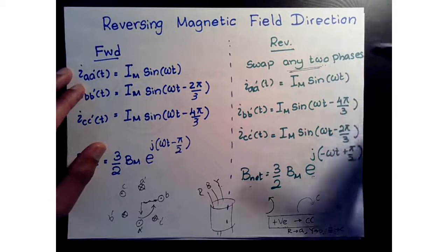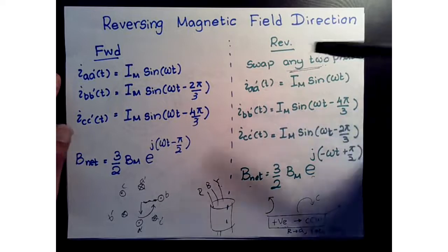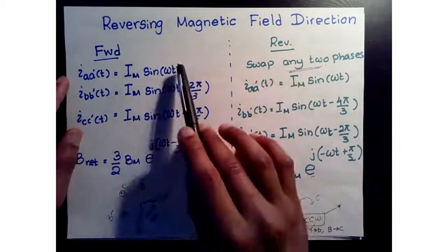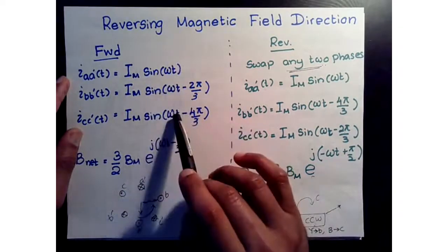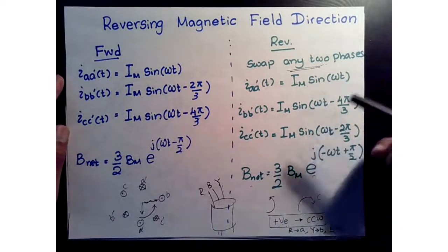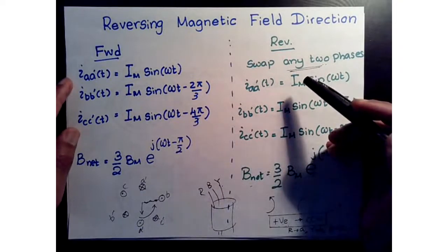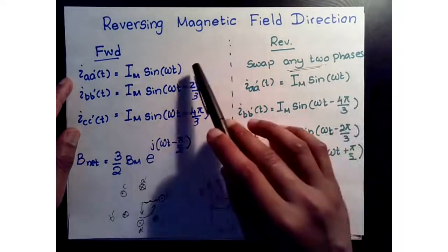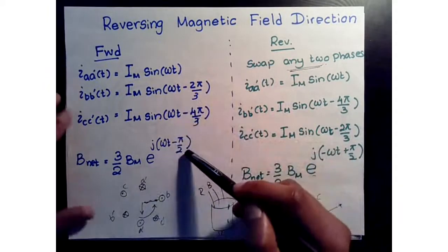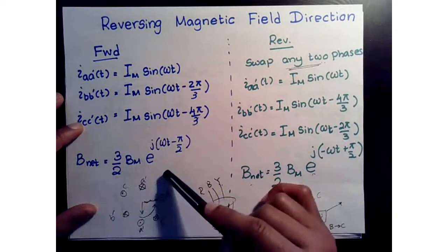In the previous discussion last time, we basically spoke about how we can set up a rotating magnetic field based on our ABC currents. This is assuming that we have a three-phase winding in our machine stator, and with that three-phase wound stator, we applied a set of balanced three-phase currents, and we showed that we have a net flux of this form.